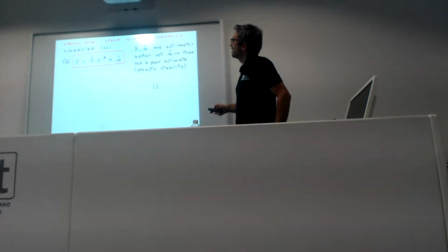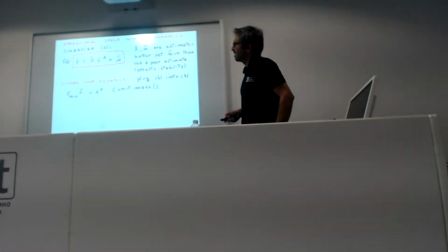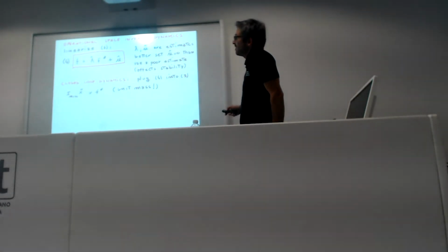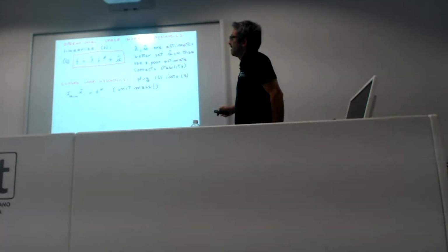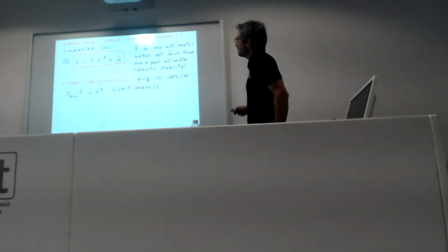And then if we replace this force into the equation of the dynamics at the end effector, we get in essence an identity matrix times x double dot equal to Fd. So it's like our robot now behaves after the linearization as a unit mass.